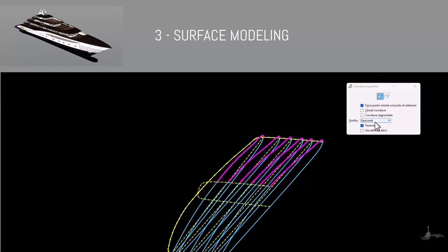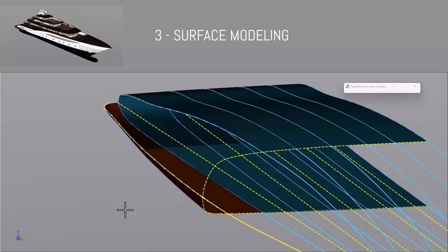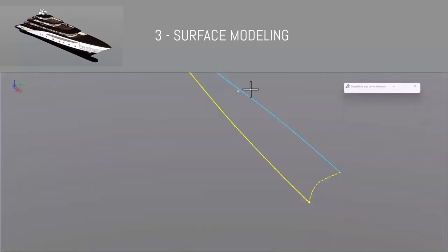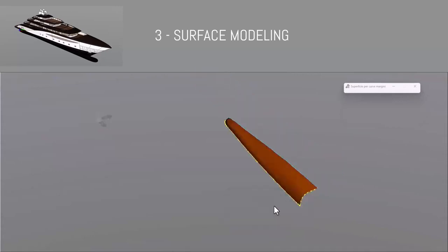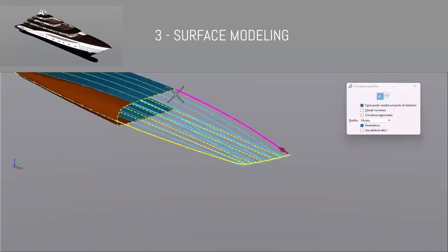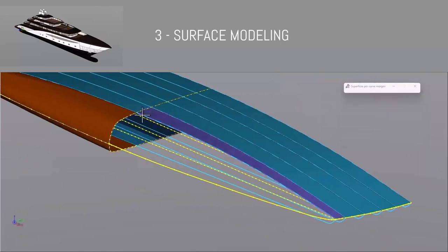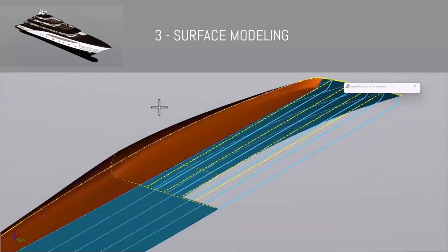Once the design of the yacht has been completed, many of these curves are the surface's edges, so you can move on to the actual modeling with them using only the construction and curvature tools. They include everything needed to properly close the contours of a surface. The curvatures also allow the control of the normals to correct the direction of construction, avoiding limits and inconsistencies immediately.